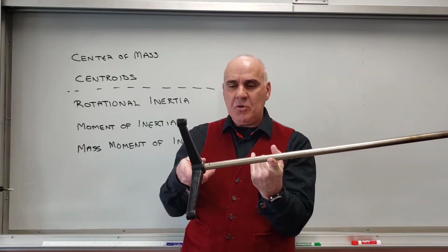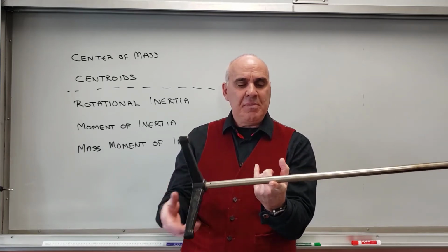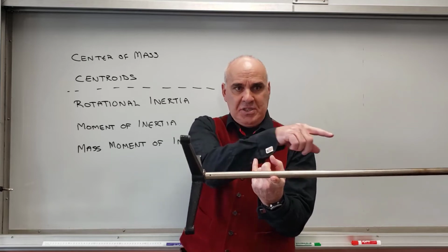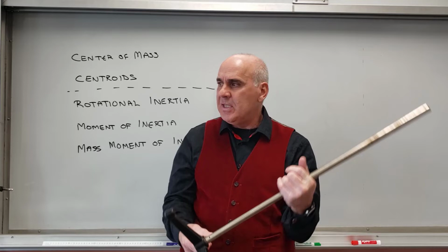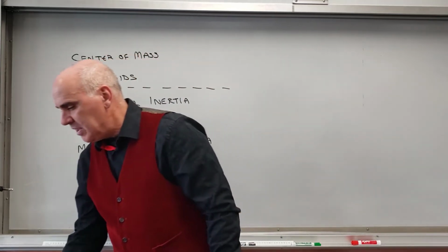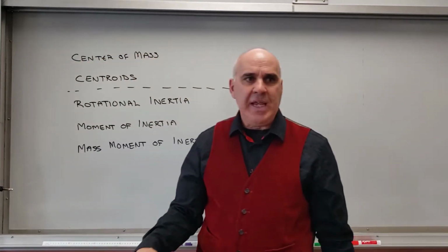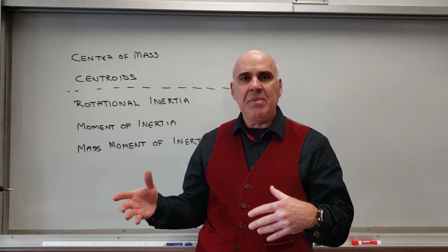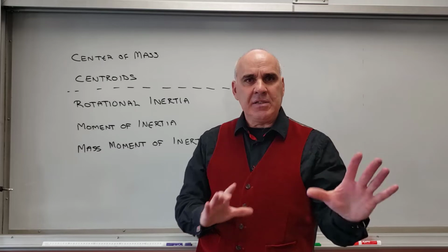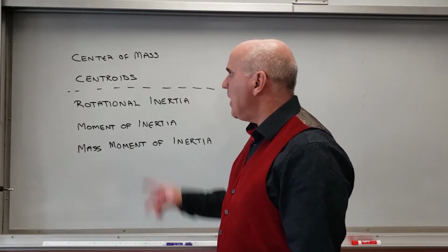All right, and there's a variety of different ways to find the center of mass. In one dimension, left and right, supporting it at that point will tell us where it is. If it's in 2 or 3 dimensions, generally what we like to do is hang it from some locations, and we'll find out where the center of mass of that would be. And I'll get to that in a later video.